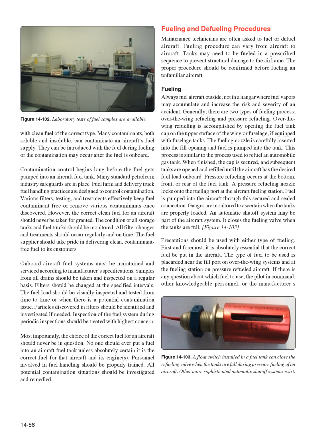Most importantly, the choice of the correct fuel for an aircraft should never be in question. No one should ever put a fuel into an aircraft fuel tank unless absolutely certain it is the correct fuel for that aircraft and its engines. Personnel involved in fuel handling should be properly trained. All potential contamination situations should be investigated and remedied.